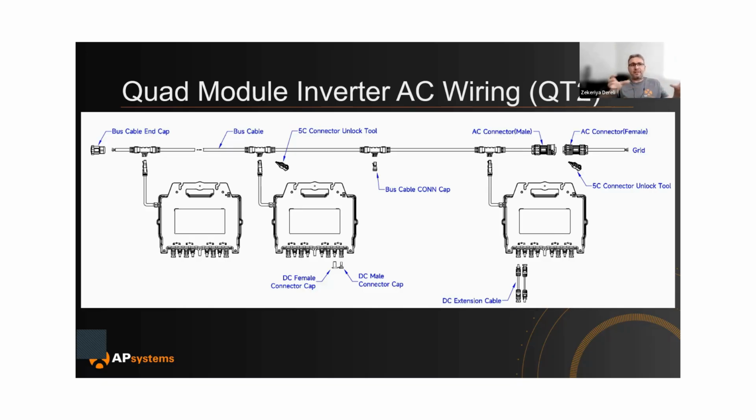I should say 4.6 meter is more common than 2.4 because it gives you more flexibility in terms of wiring. You don't have to worry about squeezing them closer together. Basically, 2.4 means you've got 2.4 meter distance between each connector. If you go with a 4.6 meter trunk cable, then you have 4.6 meter distance between each connector. So that's important, you want to choose the right one.